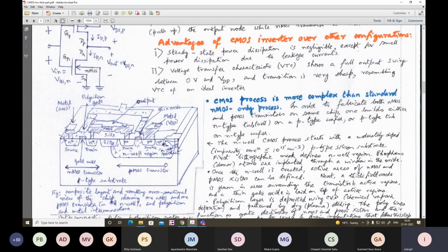Now, in general, you know that the mobility of NMOS transistors is higher than that of the PMOS transistor. So, if you build up a P well, and inside you build up the NMOS transistor, then the mobility within the well actually becomes somewhat less than it would have been in the underlying substrate. I don't know the actual reason. So thereby the mobility of the two transistors may be somewhat nearly equal, but not exactly. NMOS transistor mobility is always higher than that of the PMOS transistor.